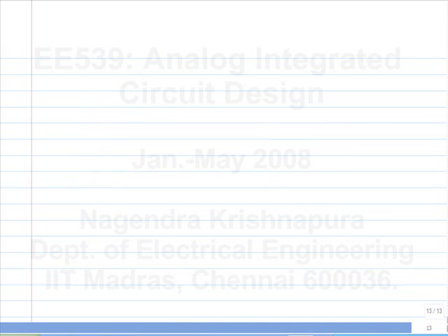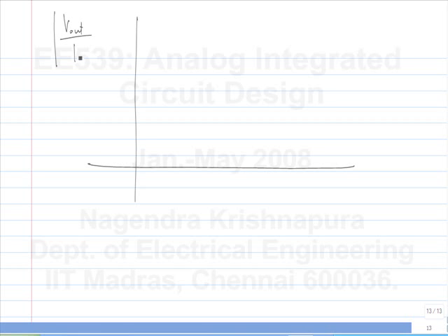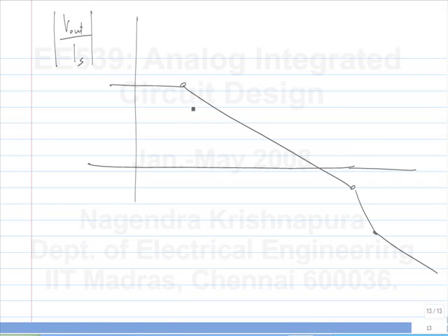So if you drive it with a better and better current source, it becomes more or less an ideal integrator. So let's say you plot the magnitude of V out by Is, and let's imagine that there is some Rs that is not infinite. And then there is a 0 also. The magnitude will do this. So this is P1, P2 and Z1.